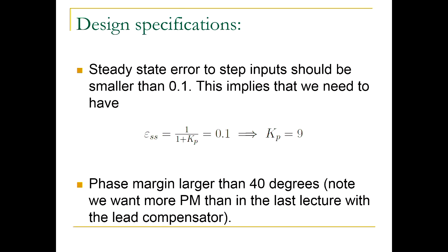Then we were saying, all right, what I want to do is I want to design a compensator that would distort the magnitude plot in this way. Something like that. I don't want to mess with the DC gain, but I would put corner frequencies of the compensator much lower than the crossover here, so that I affect the crossover frequency, but I don't affect the DC gain.